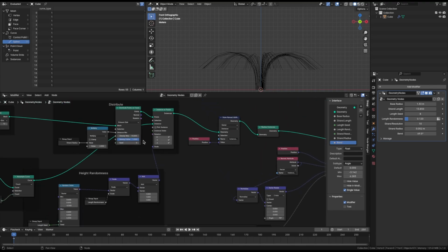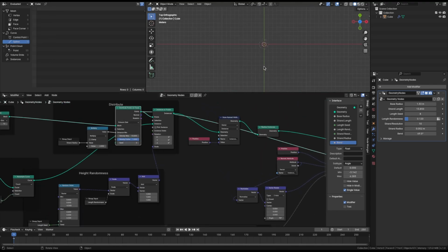So let's go look at those points again. Option Shift click, top view. We need some kind of mask so that points that are further away from the center bend a lot more than the points that are closer to the center. Again, we know that we can get the distance, the length of this vector, by just the instance position, because it's based at 0, 0, 0. It's based at the center point. So the actual position values of this will be the vector, and we'll take its length. So here we'll bend not as much in the center, and here we'll bend as much as we would expect.